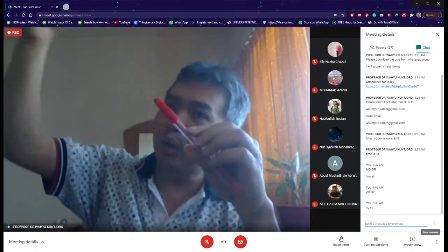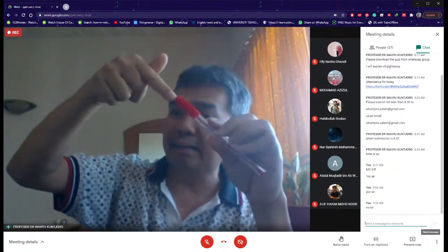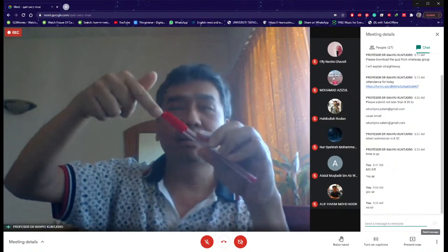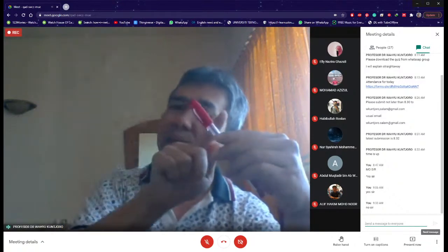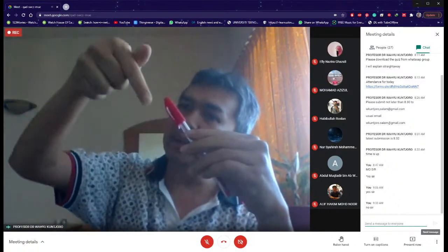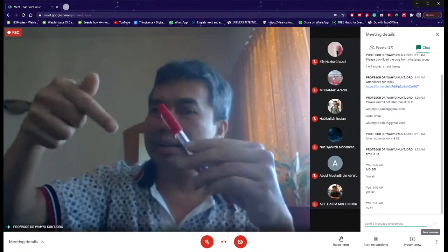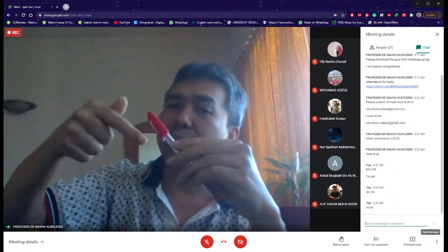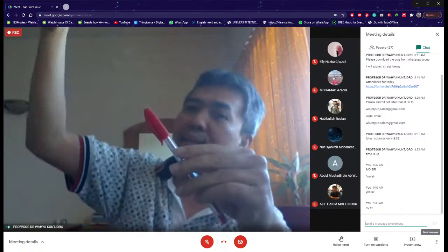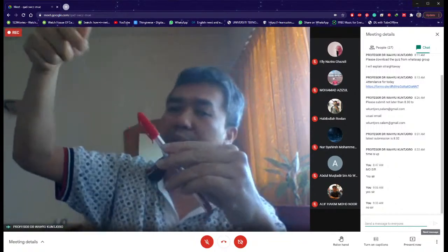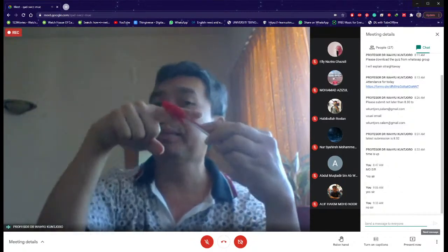But the resultant is always going to be along the axis. That is the nature of truss. If it is pin joint, the resultant of Fx and Fy actually is axial. What does it mean? It means that truss is having similar behavior to bar. Why? Because bar only has this kind of behavior, which is axial force, axial displacement.